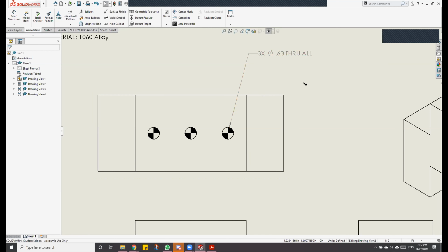If you have a part that also has dowel pins already on it that are press fit into that part, and it's going to be inserted into these holes, you have to specify that this is a slip fit hole so that the part can easily come in and out. So there are different fits for different things. And you can always Google those if you're not sure what they are. So it's important to specify.